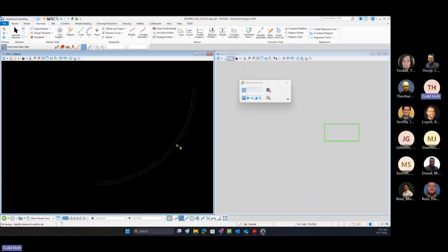If we're coming in skewed, maybe from this line to draw in, I'm going to do a line between points, just to establish that front sidewalk. Maybe I snap to this one. I can also turn off the persistent snaps on my feature definition toolbar.